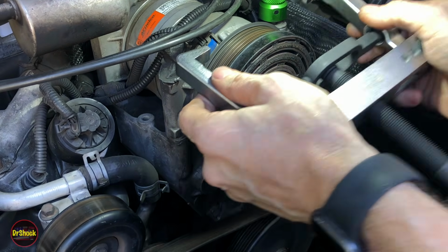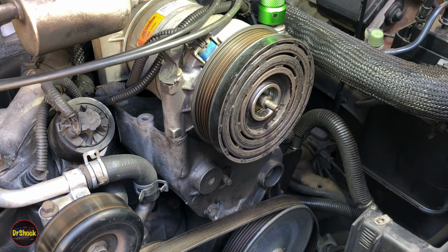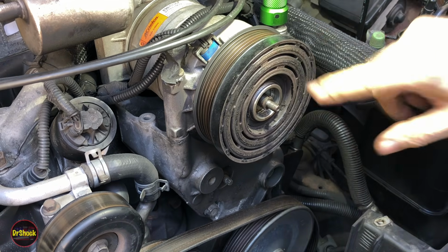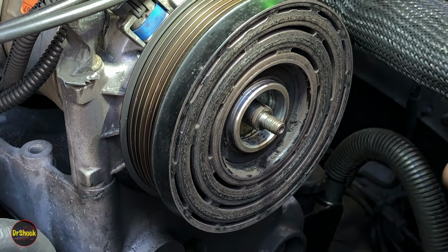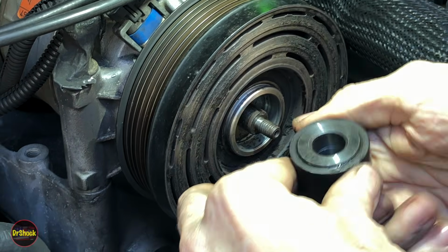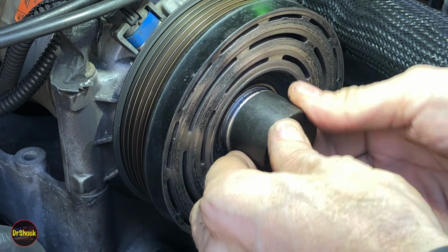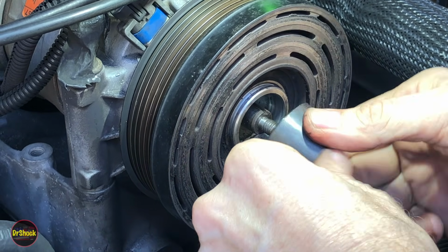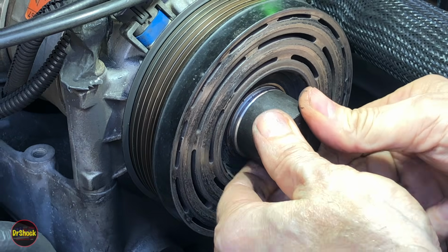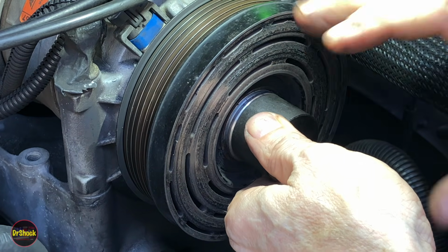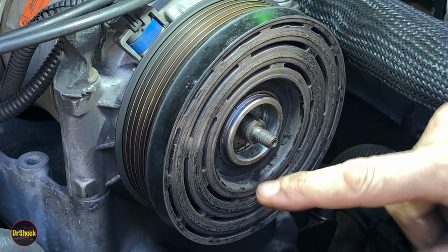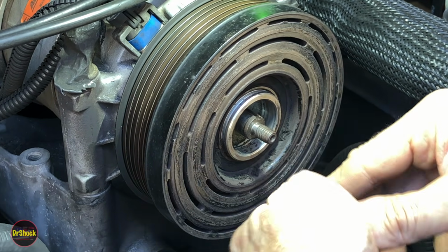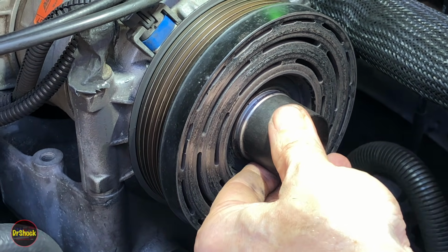Now the other thing we're going to have to do is, this is going to be under a lot more force because of the bearing, and we don't want to put that much force on the compressor shaft. So there's a pilot that sits in, it's kind of beveled to sit inside the bore of the aluminum, and it shoulders the stress onto the aluminum of the actual compressor rather than all the stress going against this shaft. So we're going to put one of these pilots in here.